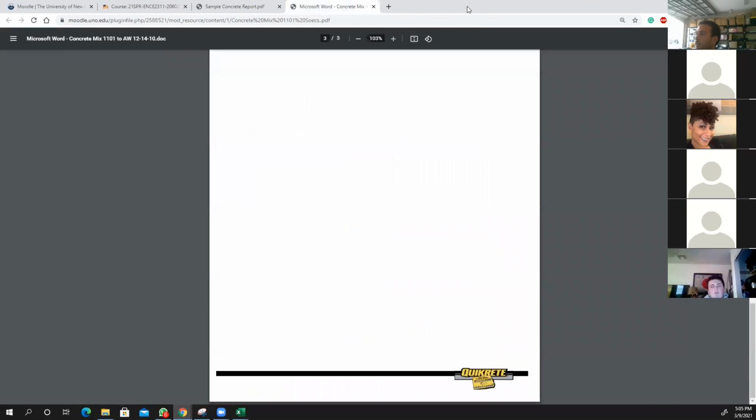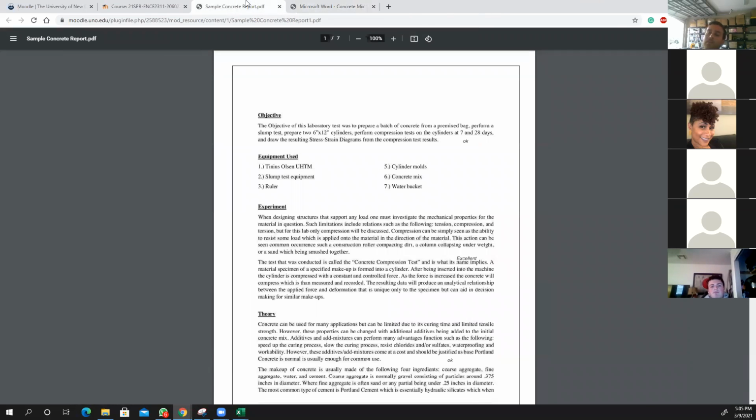All of that done before pouring? So the sample, when you said, I know you said there's 90 minutes from the time the truck leaves their facility to when it gets to you. Right. 90 minutes, is there some type of error time built in, or is it like at 90 minutes that concrete needs to be poured? 90 minutes concrete needs to be poured, and in some cases they add sugar.